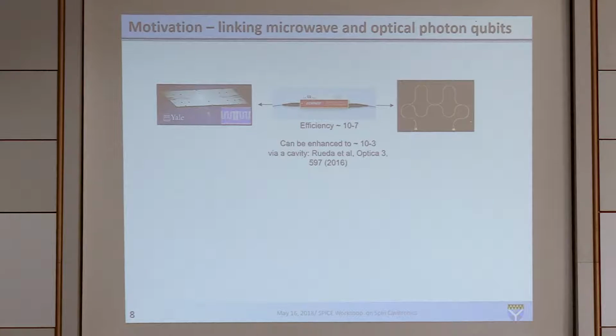So what you do is you use an optical resonator, like a lithium niobate disk, and you reduce your bandwidth. This device has a 40 gigahertz or 50 gigahertz bandwidth. If you reduce the bandwidth by 3 orders of magnitude, your efficiency goes up by 3 orders of magnitude. That's actually what can be done. Fortunately, in quantum information processing, we're not talking about 40 gigahertz bandwidth. We're talking about 10 megahertz bandwidth. So there are a lot of places where you can sacrifice your bandwidth.